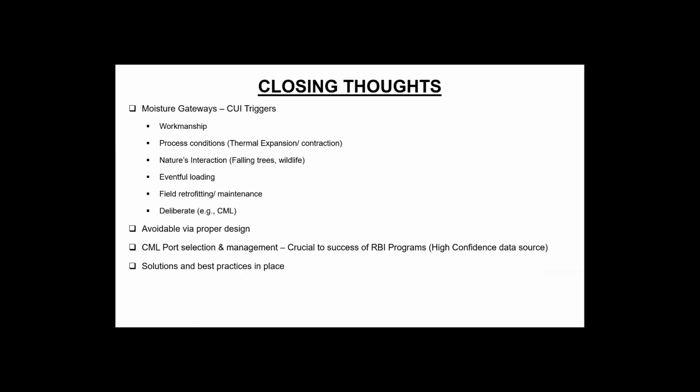So here are some closing thoughts. We talked about the moisture gateways, which are actually the predecessor to CUI events. That may come from workmanship and process conditions such as thermal expansion and contraction. So our project specifications should accommodate the effects of thermal expansion and contraction.